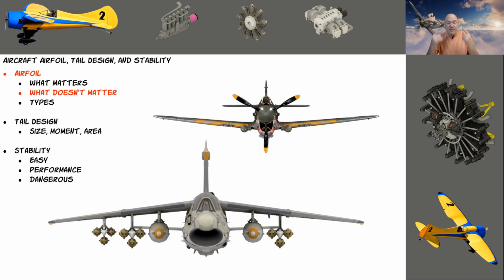For some reason in people's minds, they think we've got to have the thinnest airfoil. And there's all kinds of problems with thin airfoils. They don't produce as much lift. They have pointier noses, so they stall more abruptly. With a big round nose, the air takes a while to figure out which way to go. On a pointy nose, it decides pretty quick.